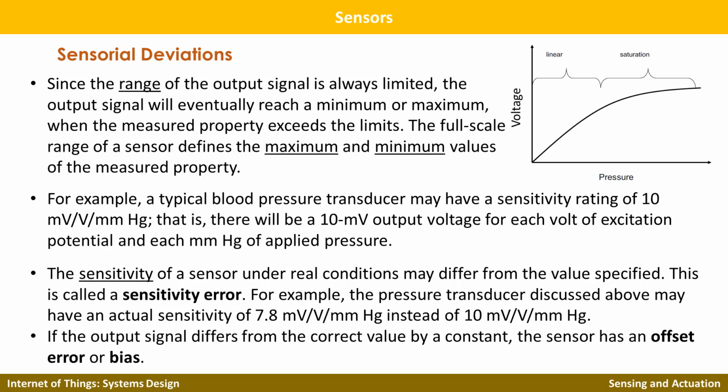As we discussed before, every sensor has a range which has a maximum value and a minimum value. Within this maximum and minimum value, you usually find a linear relationship between what you're going to measure and the electricity they produce. So you can have a one-to-one mapping using an equation roughly that if the temperature is increased by 1 Celsius, this much of electricity will be generated, or whatever the output is proportionate.